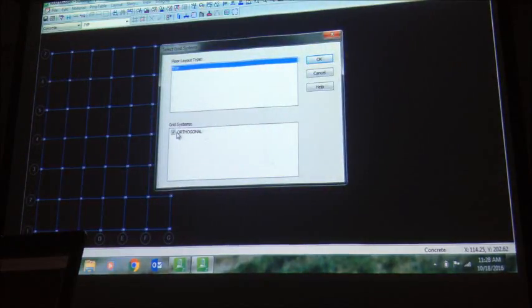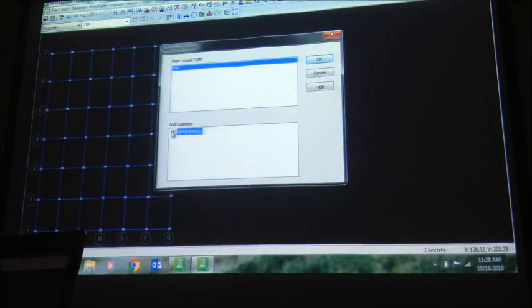Okay, yes. How do you get to the grid? Go layout, grids, create an ID. That's what I click and then nothing shows up. Oh, you are not showing the grids. Yeah. Click on this one. Okay, go orthogonal. Oh, okay. It should show grids like that. Okay. Why my grids are not shown? Because I covered them. Now it's shown.